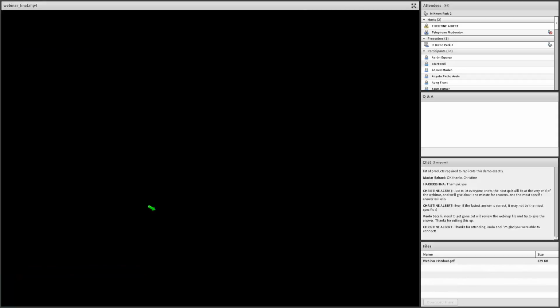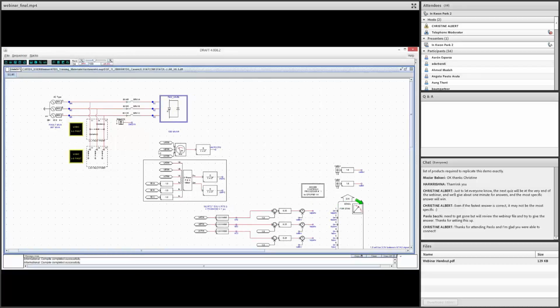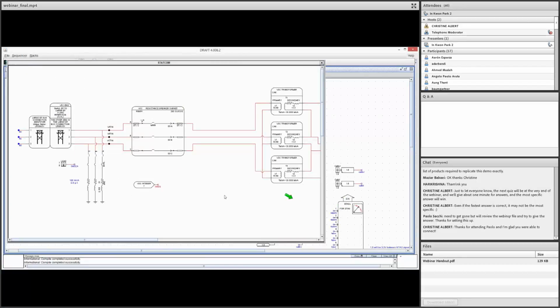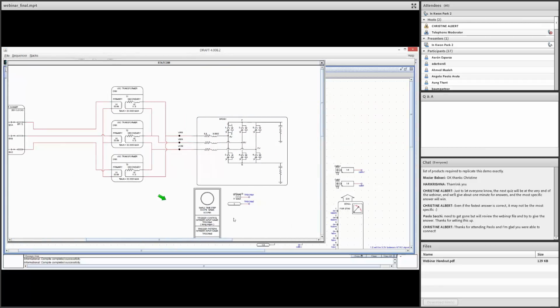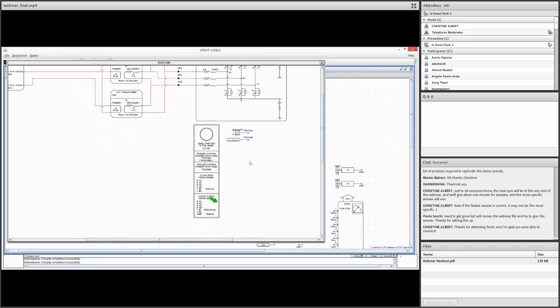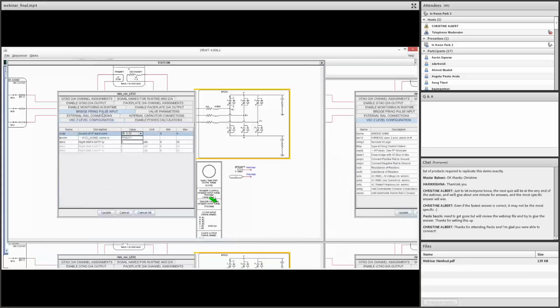Then again, now we are coming back to the simulation case. And this case is a little bit different from the STATCOM simulation case we looked at previously. In here, we don't have any control. This case only has the power stack. All these control models are only for signal conditioning. And we have a similar, or the same, power stack as before, but now we don't have any internal control. The only model inside this power stack is this real-time scope model, which allows us to have small time step simulation value observation from our RTDS RSCAD runtime.